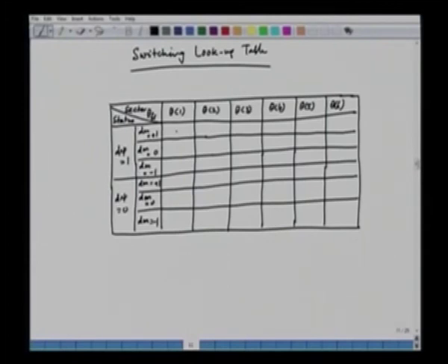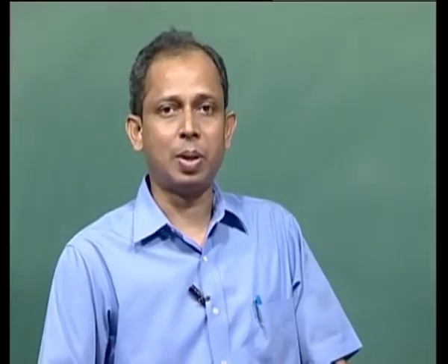So we apply here a voltage vector, that is V2. Now if we have to increase the flux but keep the status quo of the torque unchanged, we apply a 0 voltage vector. Similarly, if we have d psi equal to 1 and dm equal to -1, we apply V6. So this is how we fill up the entire lookup table here.